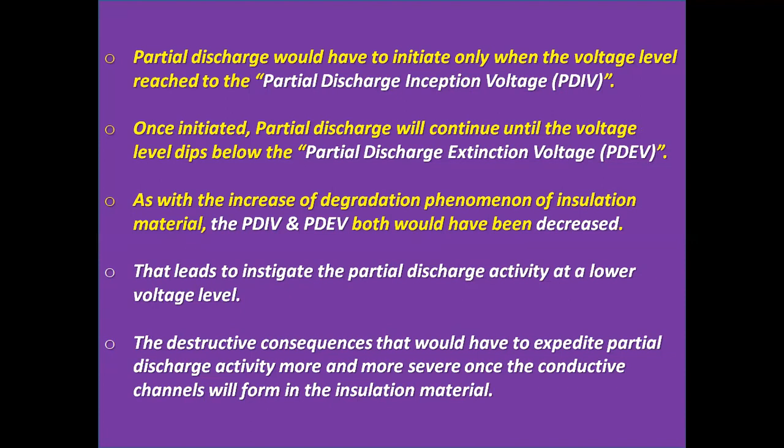With the increase of degradation of insulation material, PDIV and PDEV both decrease. That leads to instigating the partial discharge activity at a lower voltage level. The destructive consequences expedite partial discharge activity more and more severely once the conductive channels form in the insulation material.